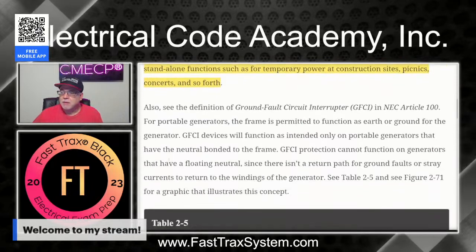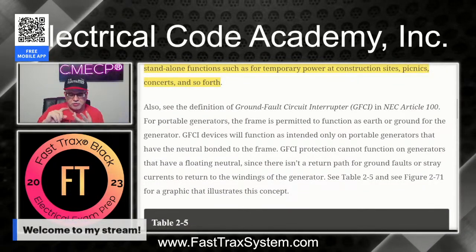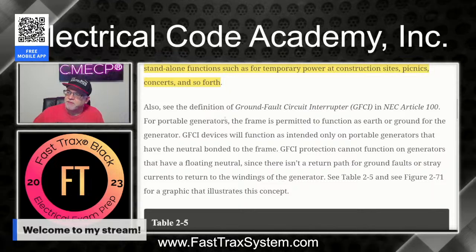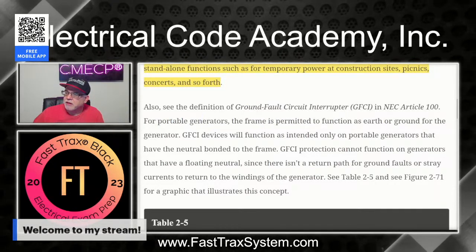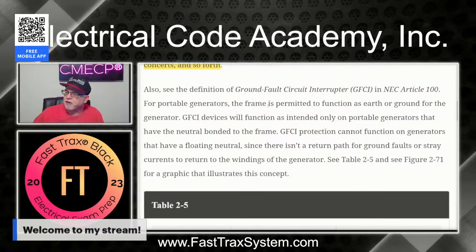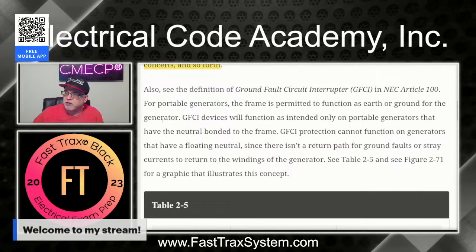Why? Because that's going to allow the overcurrent devices to function properly, and that's going to allow the GFCI devices to function properly on the generator itself. Also, as defined in the definition of ground fault circuit interrupter in Article 100, for portable generators, the frame is permitted to function as earth or ground for the generator.